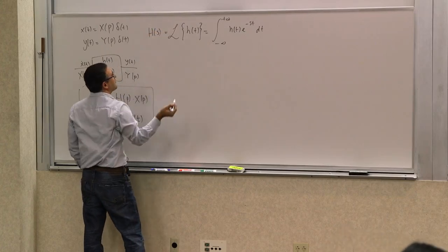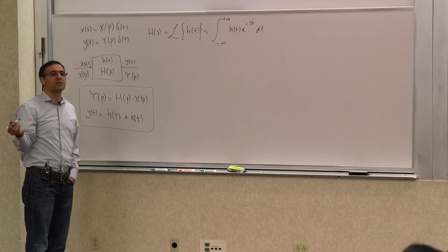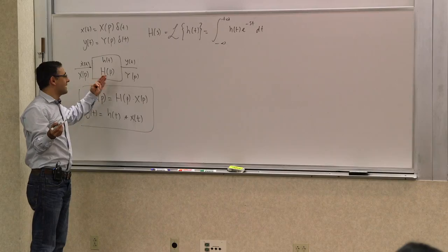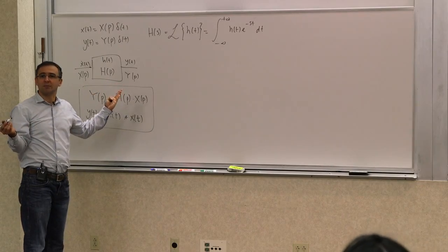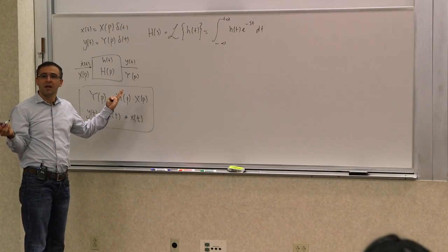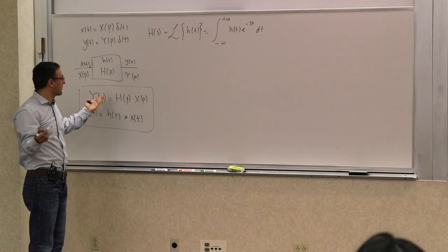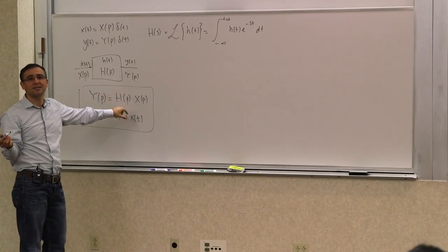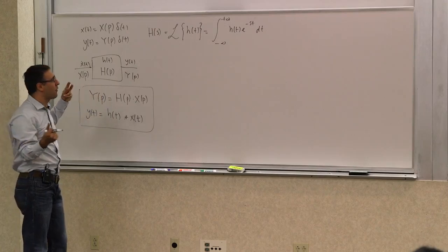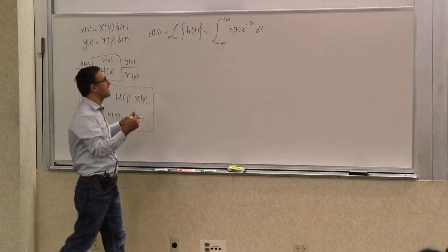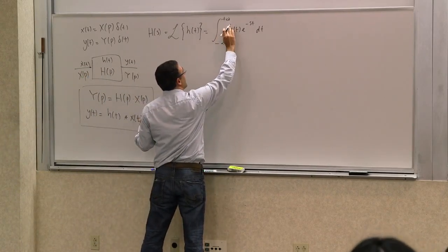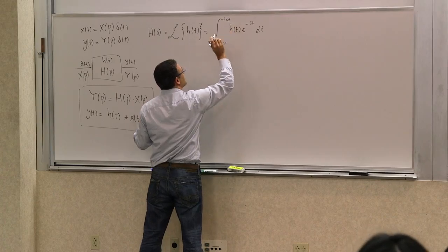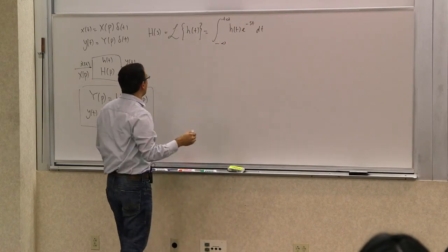And what the Laplace transform really was, was the response of a system to an e to the st, e to the negative st input. Now, what it really is, is that it was a special case of applying the operator. So the operator system didn't really need that kind of machinery and it was a more general machinery, and it didn't have to really worry that much about the regions of convergence and all those things, which with the Laplace transform you do.